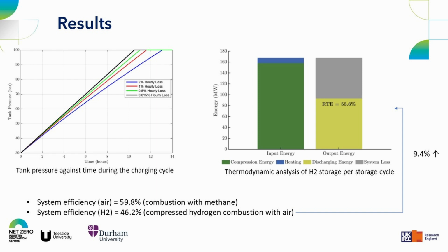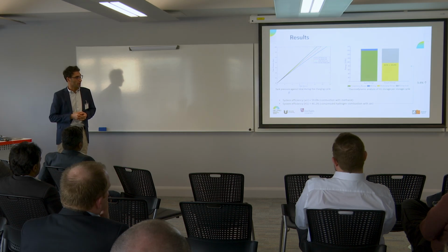We haven't stopped there yet. We are pushing the boundaries forward to increase the efficiency of the system. For now, we're checking the equivalence ratio controller, and we are also integrating the thermal energy storage system to recover the heat from the combustion and take this back and recuperate this to the system and increase the system efficiency even higher than 55%.